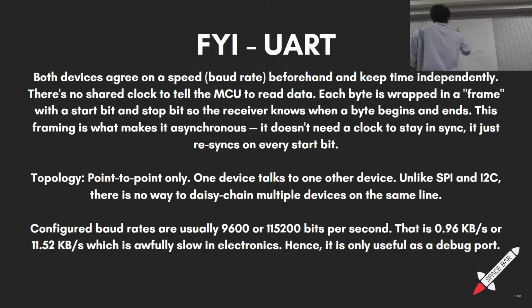Then this is your next frame. So this is one frame. This is your stop bit, and this is your start bit. And this start bit is essentially to tell the microcontroller or the device that I'm transmitting a frame. And the time taken for one frame is determined by the baud rate or bit rate.